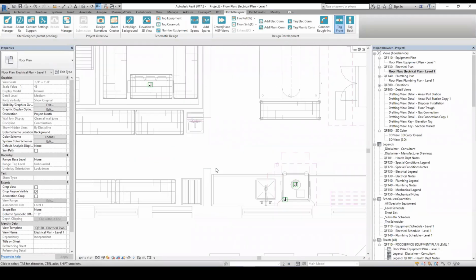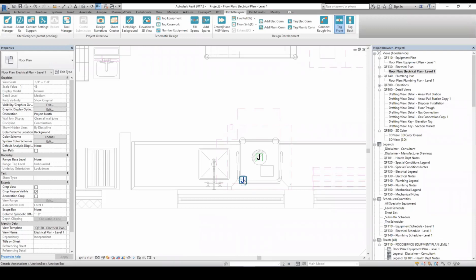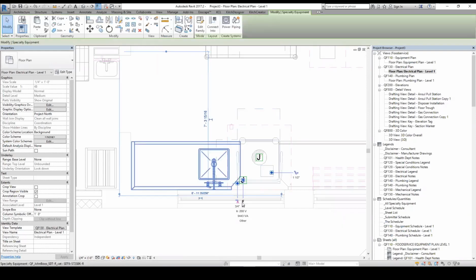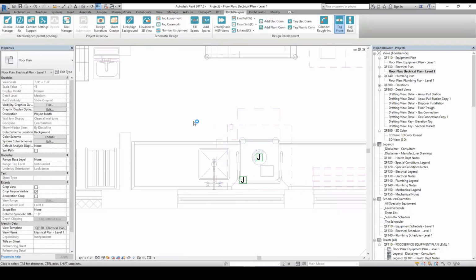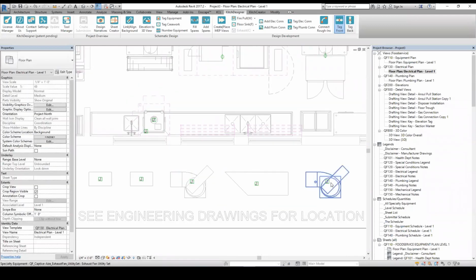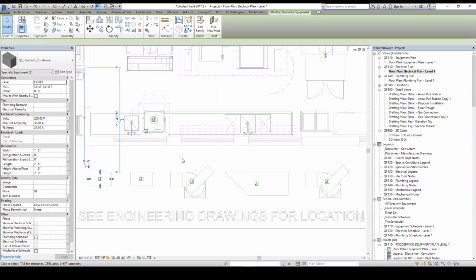So these connection points are set up to work two different ways. When there are connectors in the families, it's placing these connection points on top of those electrical connectors inside the family. And when the family does not have any electrical connectors, it's just using a default location that we set in the settings. So you can see these were probably all default locations. I don't think these had connectors in them. They're all in the center of the families.